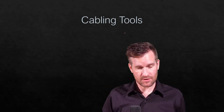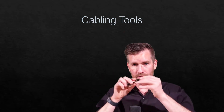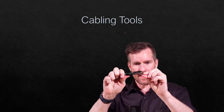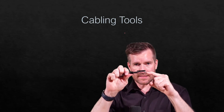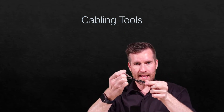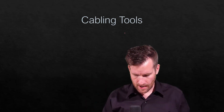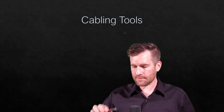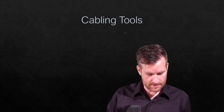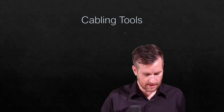Or if I need to strip the sheathing around the cable, I have a special tool. This is a little razor blade that's in there. And then this is a little piece of metal that just keeps it tight against there. And then you roll this around the cable and the sheathing will come right off. And so you can set the depth to make sure that it doesn't go too far and dig into the conductors at all, because you don't want it to dig into the conductors.